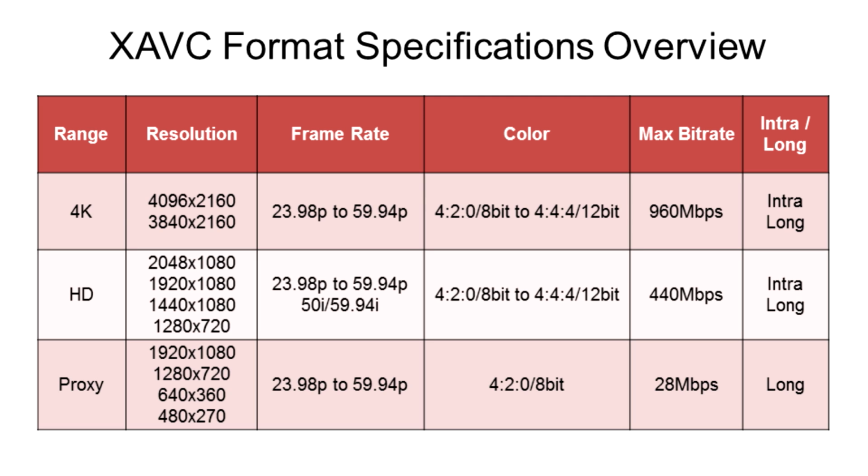We can create proxies, videos at very low data rates using the long GOP or multi-interframe compression, passing through HD at data rates of up to 440 megabits, either in intra-frame or inter-frame compression, and the maximum capability will be to reach 4K at 60 frames per second, with a maximum data rate permissible by the algorithm of 960 megabits per second. Again, the implementations of this algorithm can be selected to be intra-picture or intra-frame compression, or long GOP or inter-picture compression.